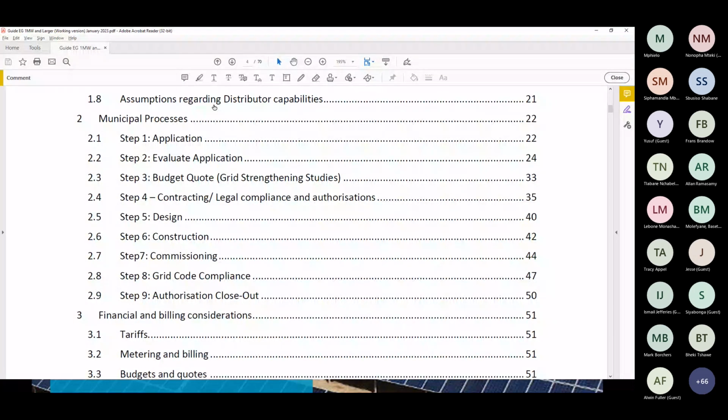And that's also on both sides, but making sure that your generator actually understands what's important there and that is critical to get the protection coordination and those things like getting the timing, the sync check, to get that right between the different parties.